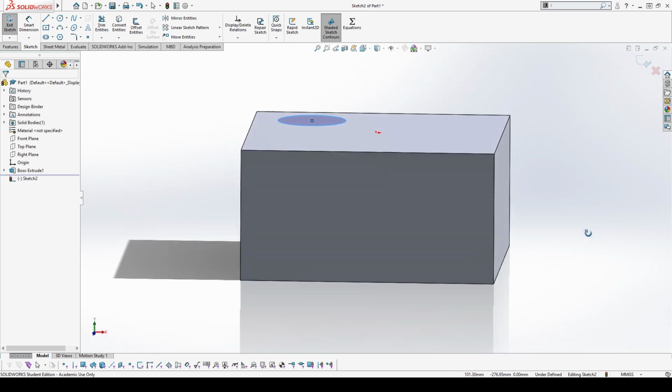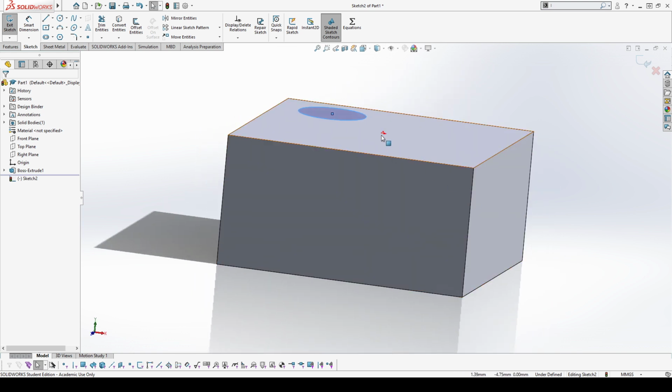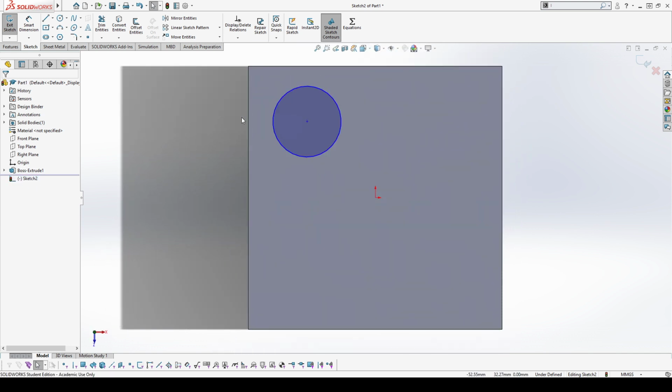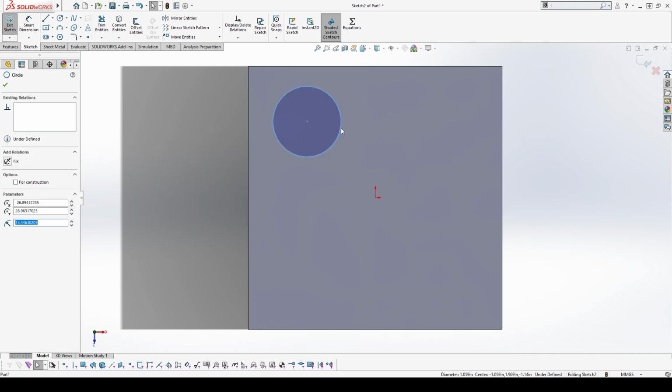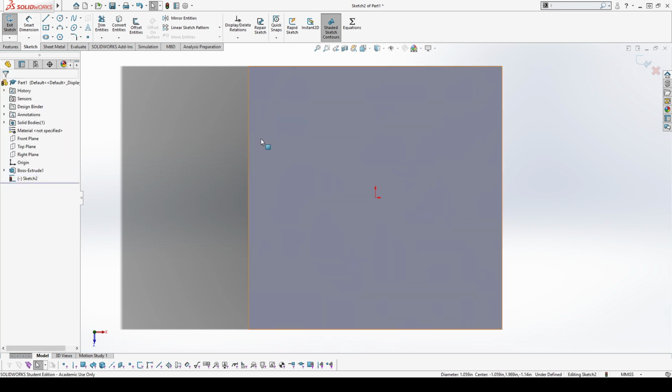And you'd see my sketch of this box, and my sketch origin is right in the middle of that face now. So I'm going to right click on the sketch, click on normal to get back to that normal view, and I'll delete the circle. But let's say that I wanted to bring in this face, and actually these lines on the outside, to use in part of my sketch.